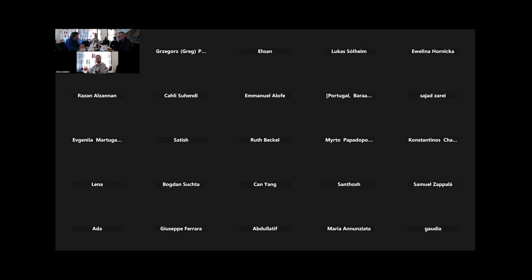Or there are also some color codes, so we are sure the blue color is the first channel, and that's a single mode. The brown color is a multi-mode channel, and the color code is always used when we have some commercial cable that has more than one core inside, and usually we have at least 4 cores inside or more.